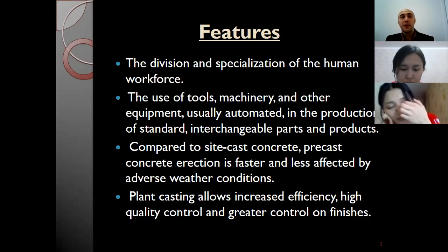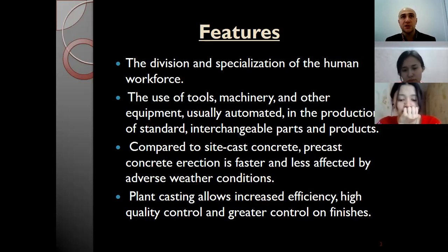As we know, monolithic constructions require time for installing formwork, installing reinforcement, time for the concreting, so applying the fresh concrete, and time for waiting until the fresh concrete is hardened, then time for removing the formwork, and so on.